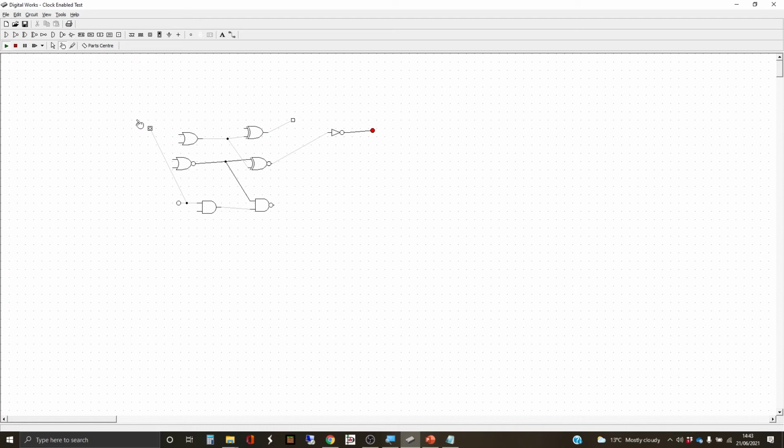Similarly, this interactive input is acting as if it's a gate that only has an output. I hope you can get your head around that. It's a little bit confusing because it's called an input, and it is an input because you can interact with it, and it can take information from the user. But in terms of the circuitry, it's treated as an output. And so you can't put two of those together. Again, for obvious reasons, because the question would be which one of those actually determines the state of that wire that's connected the two together.